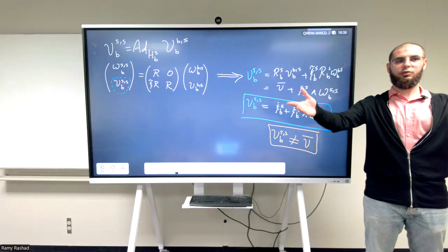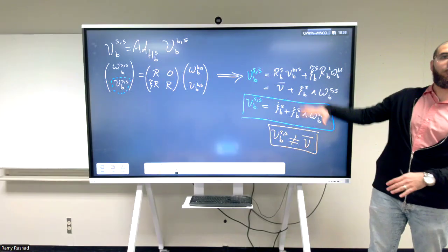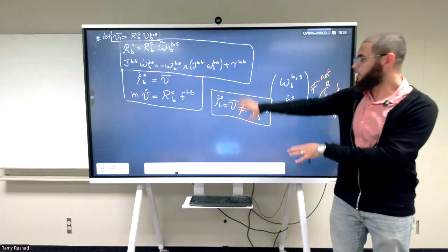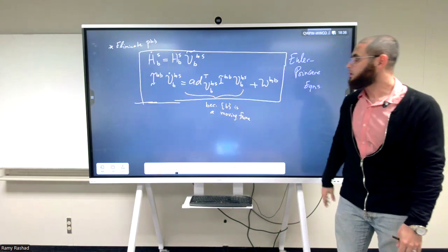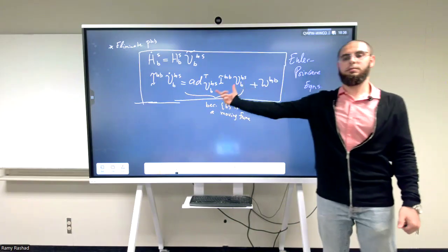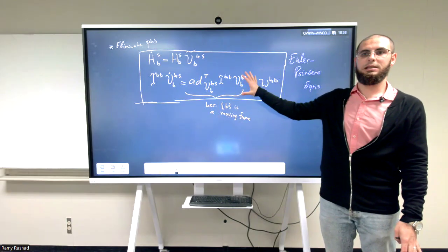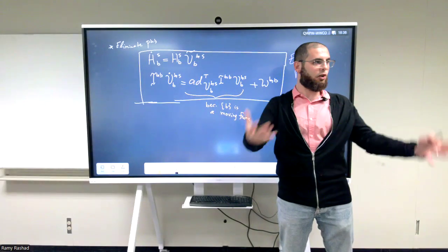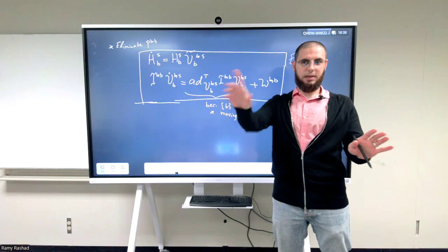It makes sense that you forgot this stuff. That's actually good news for you, because it's very hard to work with in real applications. What I'm showing you is that all of this stuff related to Coriolis and gyroscopic terms and all of this complicated stuff is incorporated in this very simple equation. They're all just encapsulated in one term. You know exactly how it changes coordinates from any frame to any frame, and you can do everything in this simple expression by just preserving the fact that you're using a twist, and the twist has a group structure. Okay? I'll stop the lecture and I'll take questions, okay?